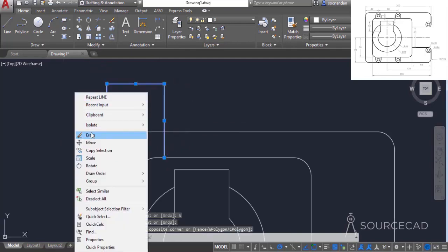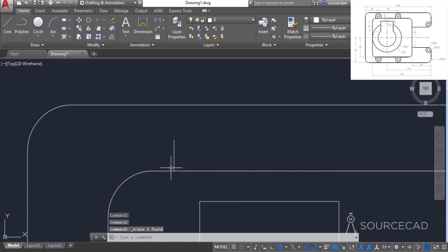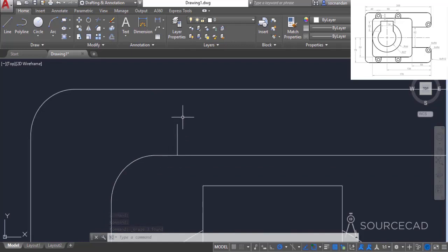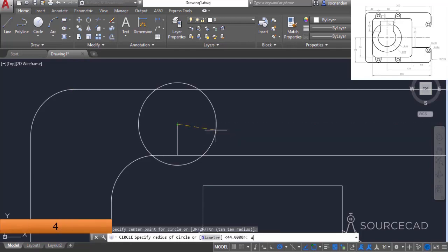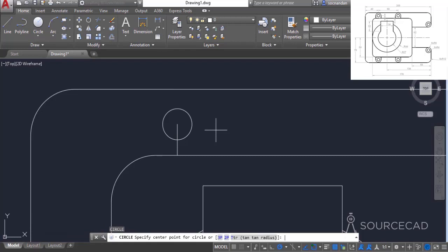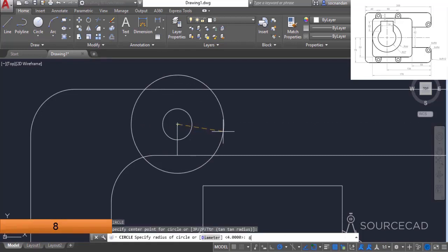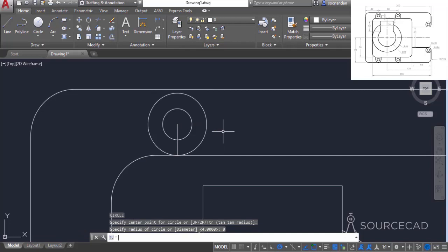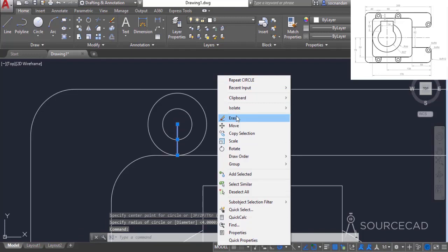These are no longer required, and you'll see that we have this line which will provide the endpoint of our circle. So go to the circle tool now and select this endpoint and make a circle with radius of 4 units and press enter. Now press enter again to repeat the circle tool, click on the same center point and enter a radius of 8 units and press enter. And here we have it, both of these circles. Now we can remove this line, it's also not required anymore.